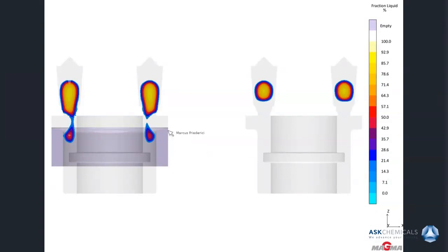Because now, due to the huge energy I put in through the padding, the solidification time of the component rises a lot. And as you might know, the solidification time also determines the modulus of a casting. That means now we have an issue: I have a riser on top, and I have a small section here which could not be fed anymore, because we need a little bit more feeding power.